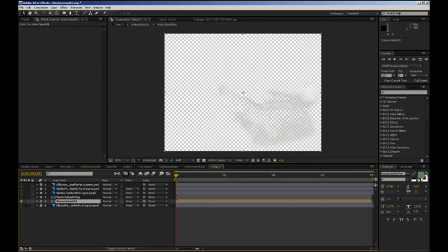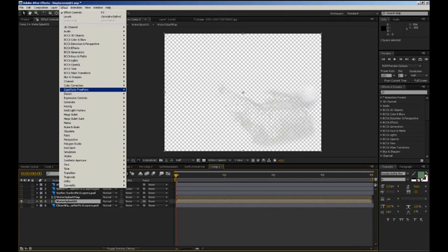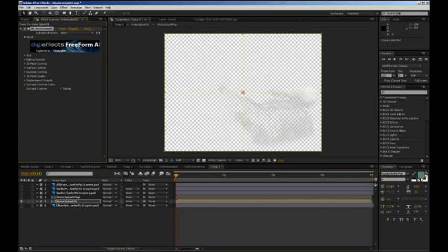Okay, and then apply Freeform to the water splash. Go to displacement control and use the water splash map Luma. I'm going to set displacement height to 70. For the 3D mesh quality, I'm going to lift the mesh subdivision to 30 and then high for the anti-aliasing.